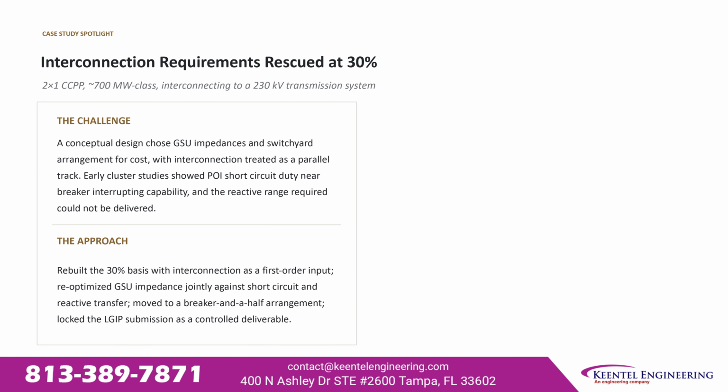The approach: rebuilt the 30% basis with interconnection as a first-order input, re-optimized GSU impedance against both short-circuit and reactive transfer requirements, moved to a breaker-and-a-half switchyard arrangement, locked the LGIP submission as a controlled deliverable.